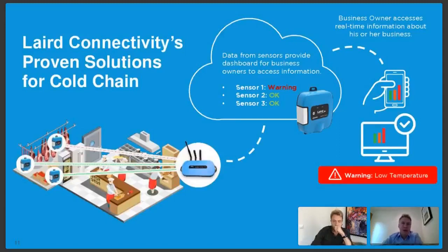We then generated this package solution with integrated temperature and humidity sensor ICs, 2 AA batteries, the LoRa and the BLE radios, and put that into a secure rugged IP65 enclosure that can then be placed within any of these environments that this icon is showing.